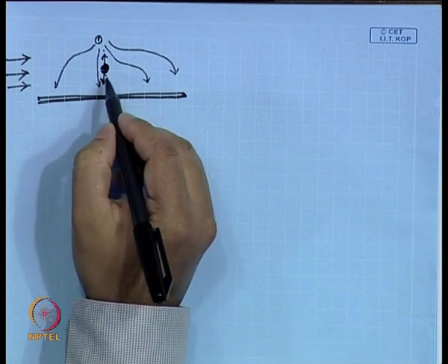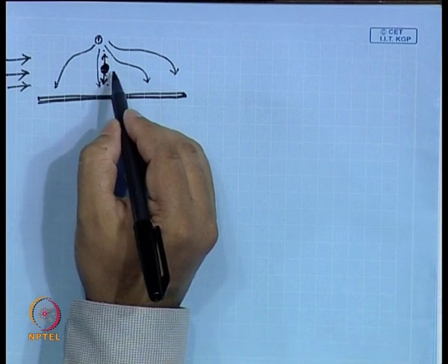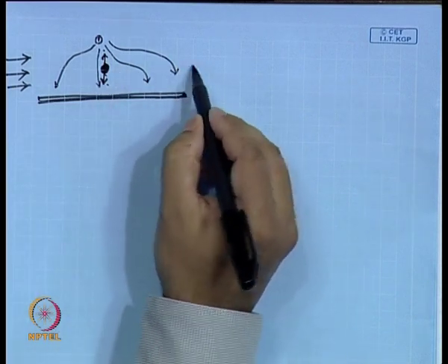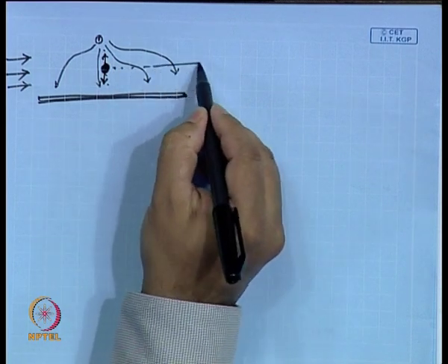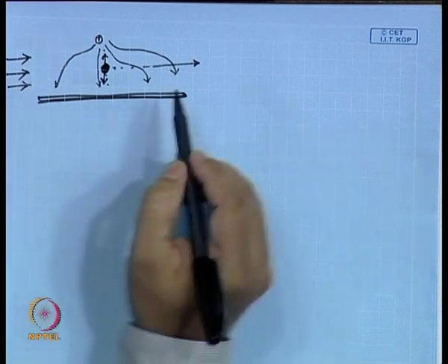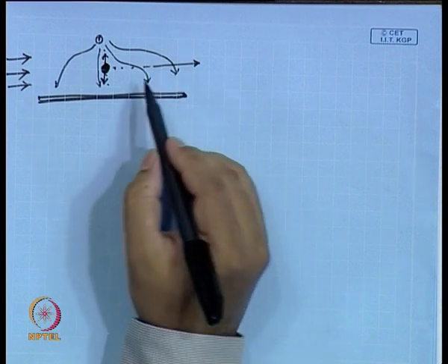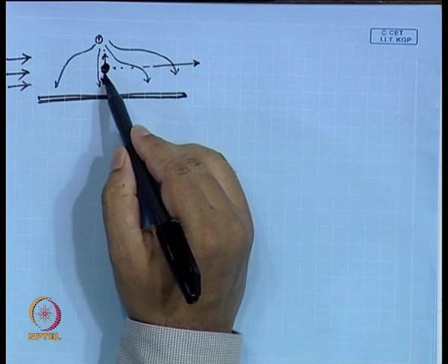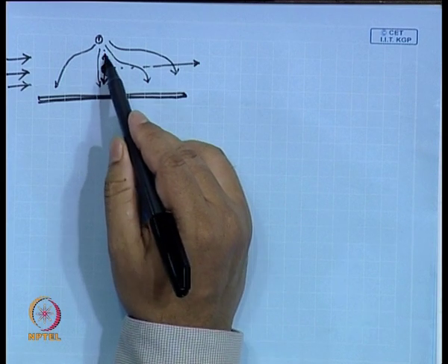So, there would be a balance between them, and wherever this balance is satisfied, the particle will be settling at that layer. And when these elutions take place, whenever a particular layer is eluting, which is governed by the parabolic velocity profile, that will come at the outlet. So, here it would be a balance between the gravity force and the DEP force.